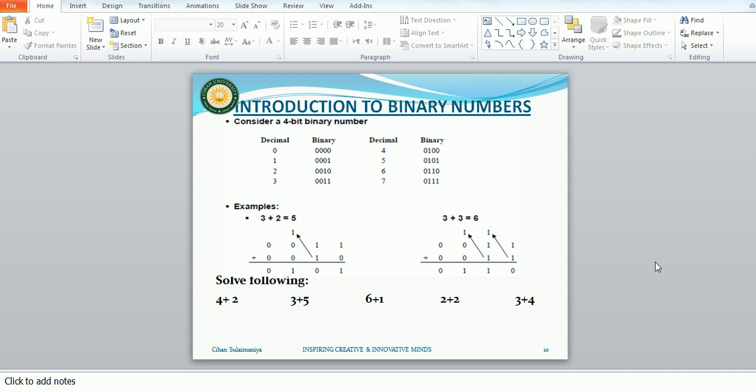But before that I have to explain how the arithmetic logic unit calculates plus and minus. Actually there is no minus, no subtraction in the arithmetic logic unit. If there is subtraction, for example a minus b, actually the arithmetic logic unit is going to do a plus minus b. It's not going to do a minus b straight away.